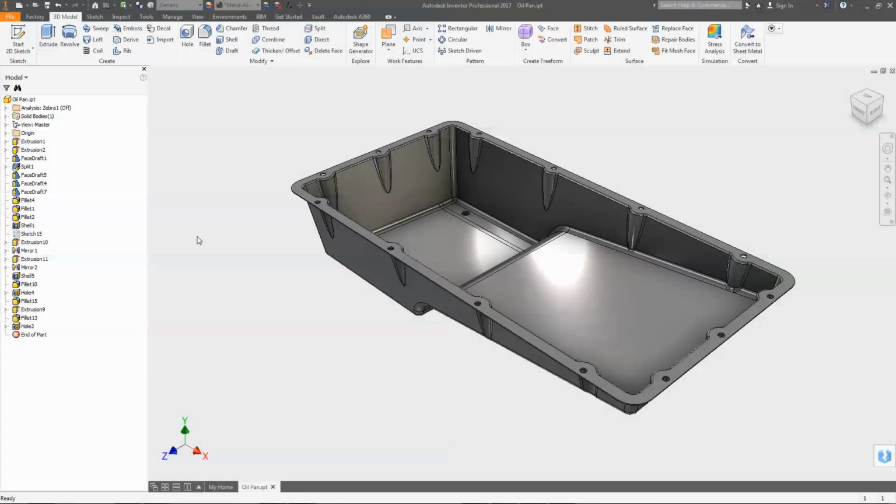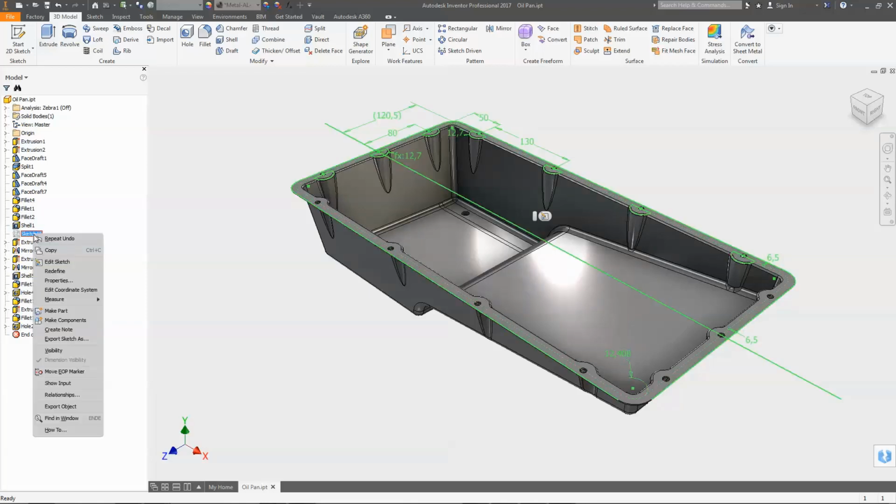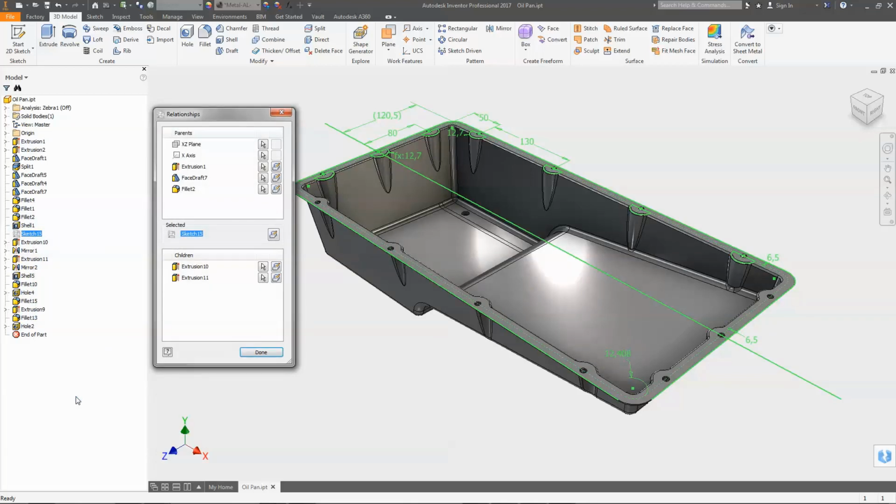You can see a quite complex model. You can't say at first view how the part has been modeled. I'd like to know what dependencies Sketch 15 has and what purpose is behind the sketch. I selected Sketch 15 and used the new Relationships command.